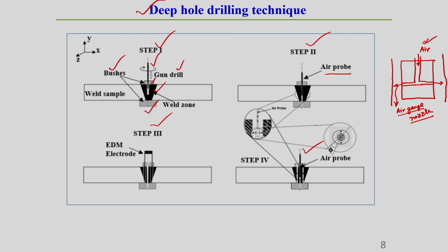So, this is called an air probe. It is a mechanical type of gauge which is used to measure an internal hole, and it can have some other applications also. Air probe is also sometimes called an air plug gauge. It is generally made of a precision ground hardened steel body.